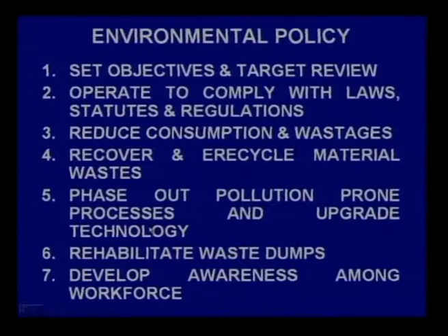upgrade technology. An example that I have quoted earlier and I can quote again, in the copper metallurgy, the traditional roasting and reverberatory smelting processes were extremely pollution prone. Not only did they generate pollution, they also wasted energy. So, the technology was upgraded to flash smelting, and in some other countries it has gone to the level of continuous copper smelting.